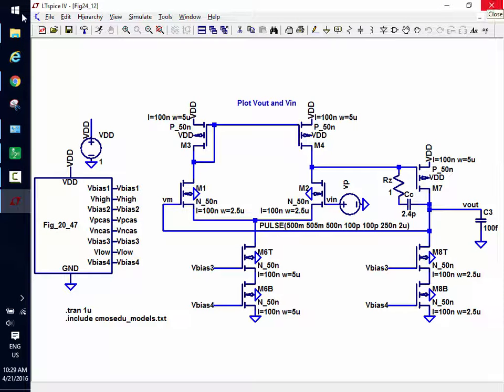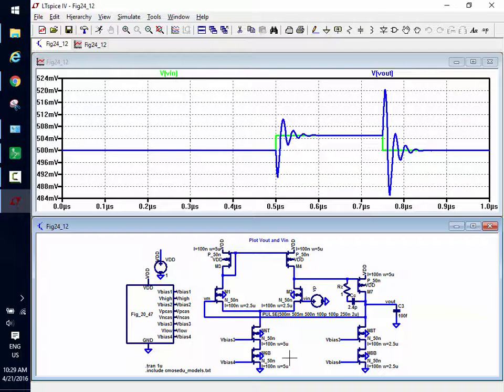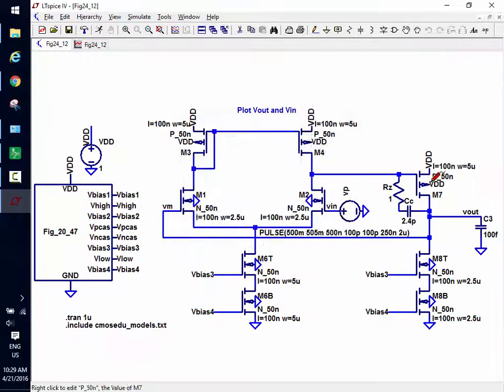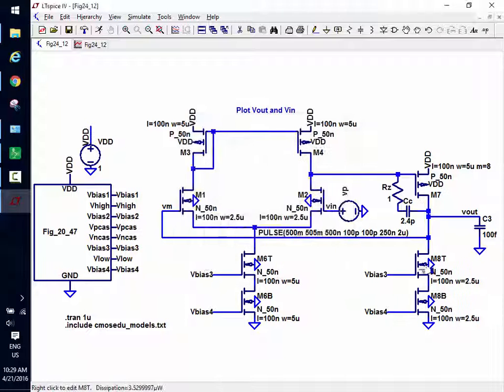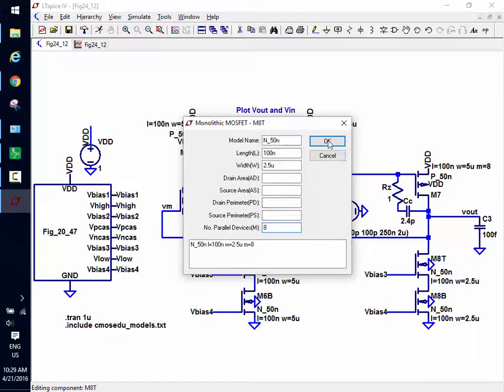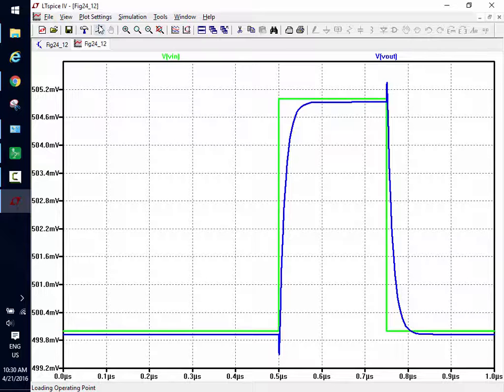Transient. Let's do it a different way. Let's look, see how that's messed up? So let's see what happens. It has the 0, but let's see what happens if we move F2 out further. So let's do the same thing here. Let's say that's 8. I don't know if it'll do anything because of the 0, but we'll find out. Hey, I moved F2 out. That 0 is even still there, but now that F2's moved out, it's more stable. Let's see what happens in the phase response.